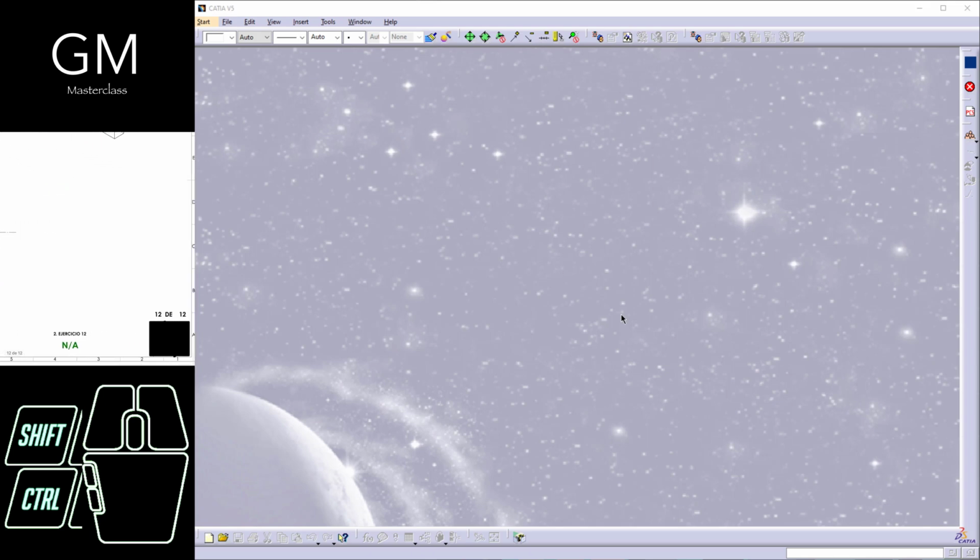This information of the unit system usually comes right here, taking into account the normativity for the draw, but it usually comes into a box that not only tells me the material, also tells me who did, or the person who did this engineering draw, the person who checked, the unit system, of course, the date, and some other aspects. So as I said before, I can assume that these are millimeters, and we can start doing this engineering draw.